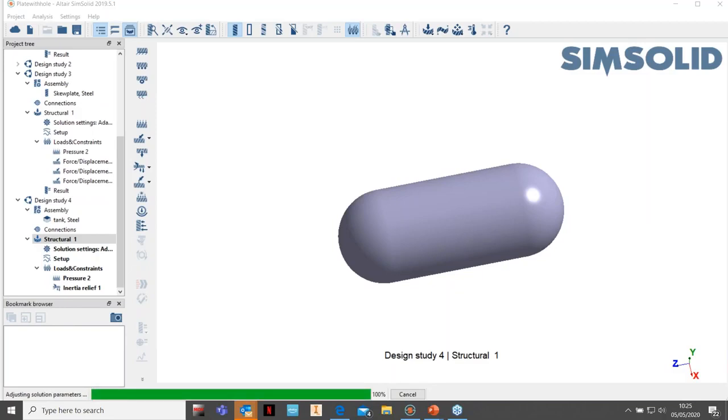Okay, let's just see. Typically, something like this, you would run it as a quarter model or 1/8 in Inventor and Nastran. And even the test sort of suggests that you use it as a quarter model or a half. But I just want to show you what type of results we get with this inertial relief.